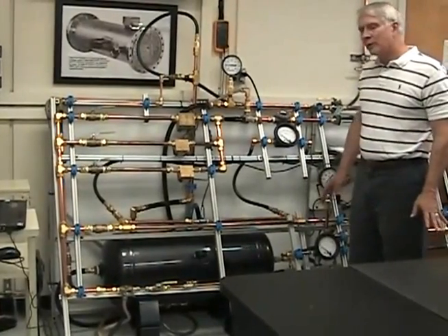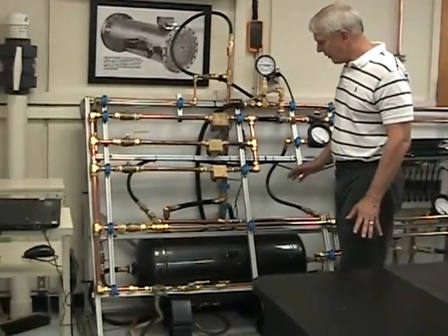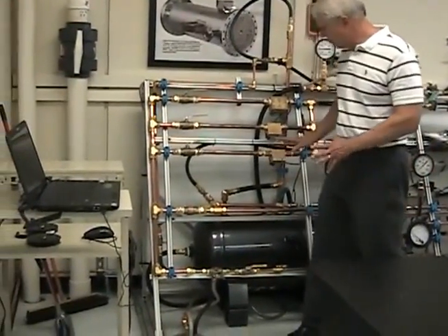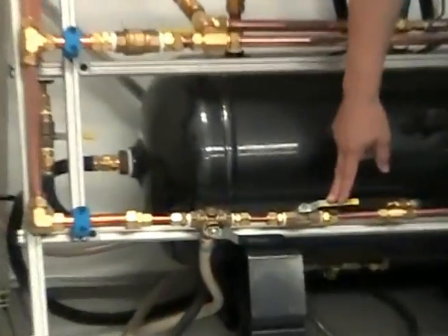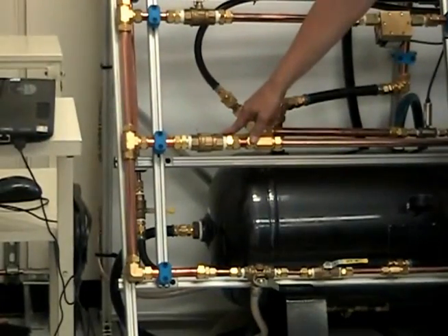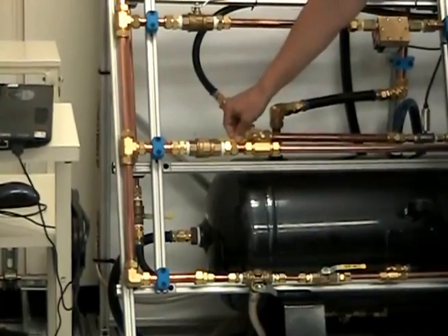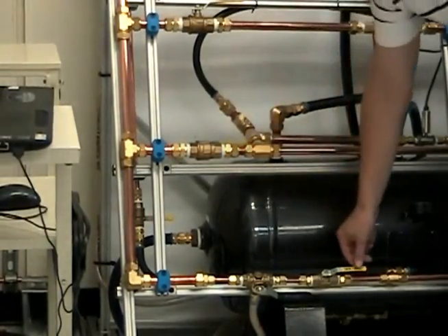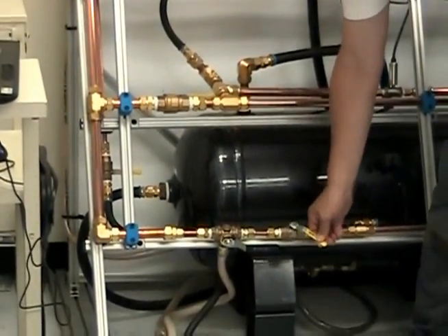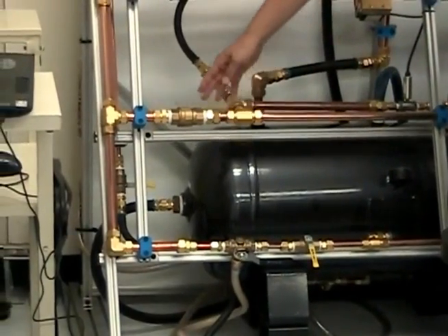All right, in order to get the water to go where you want it to go, we have two valves. There are more than two valves on the system, but there are two important valves. There's the valve here on this small pipe right here, and there's a ball valve here on the large pipe. In order to get the flow to go through the large pipe, we open the large valve, the handle will be in line with the pipe, and we close the small pipe, so it'll be at a right angle to the flow, like that. Okay, so now the flow will go through the large pipe.